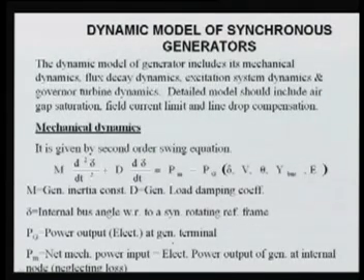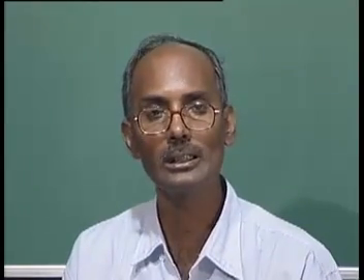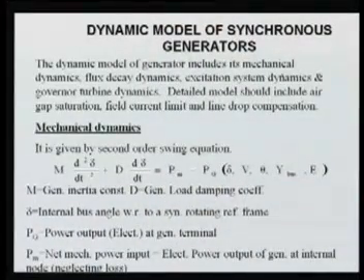have to model this excitation system dynamics, and also we have to model the governor turbine dynamics, because the governor of the turbine that gives the input to your synchronous machine may also work and it may change your mechanical input power. So if your study is for a long time, then this dynamics is also very important. So we have to include all these dynamics, including your mechanical dynamics, machine's flux decay dynamics, excitation system dynamics, and your governing system dynamics.